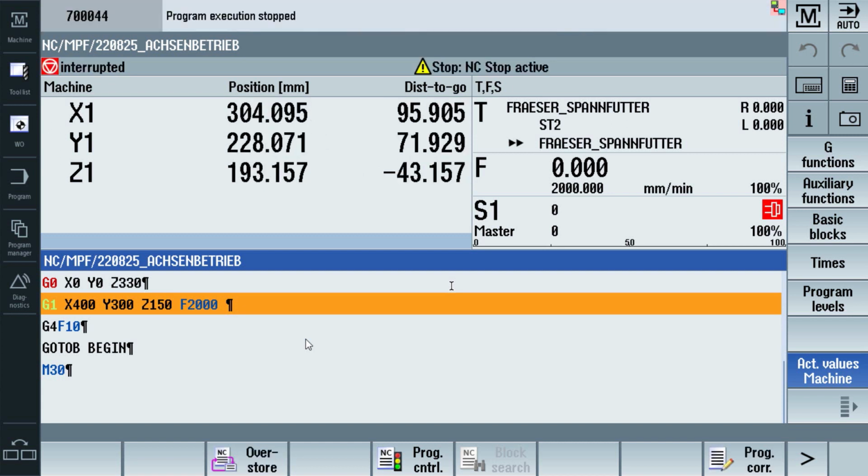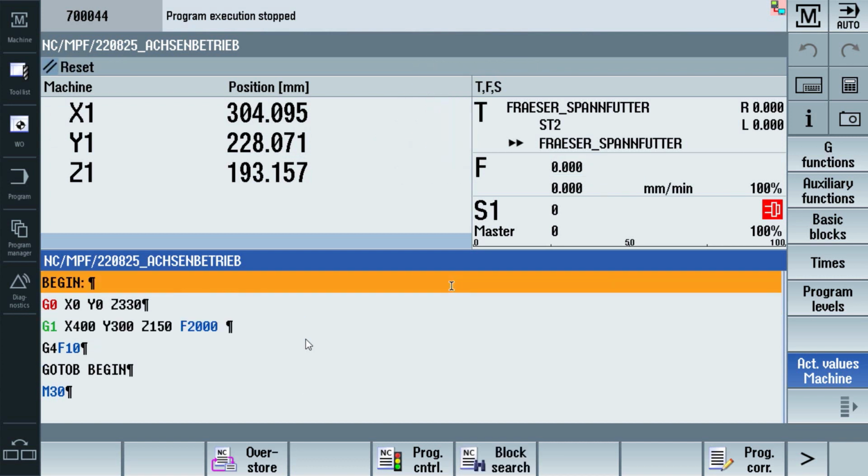So that was the second tutorial. In this tutorial, you learned how to work with SINUMERIK low-frequency data, so simple polling operations for reading and writing variables. Also, we talked about how to work with data subscriptions and how to set user alerts on the NCU. The next tutorial will be very special because we will work with high-frequency data coming from the SINUMERIK, and after that you will be able to calculate a floating average over a signal to a dashboard.